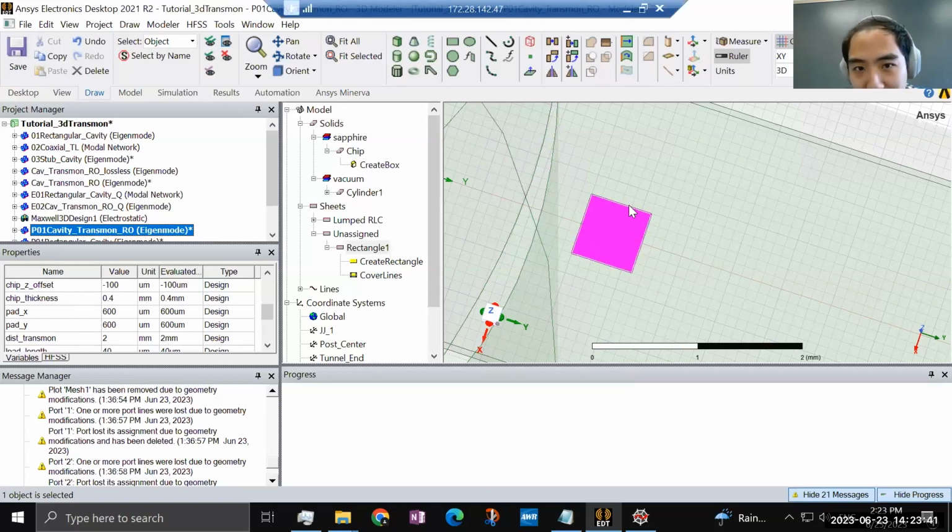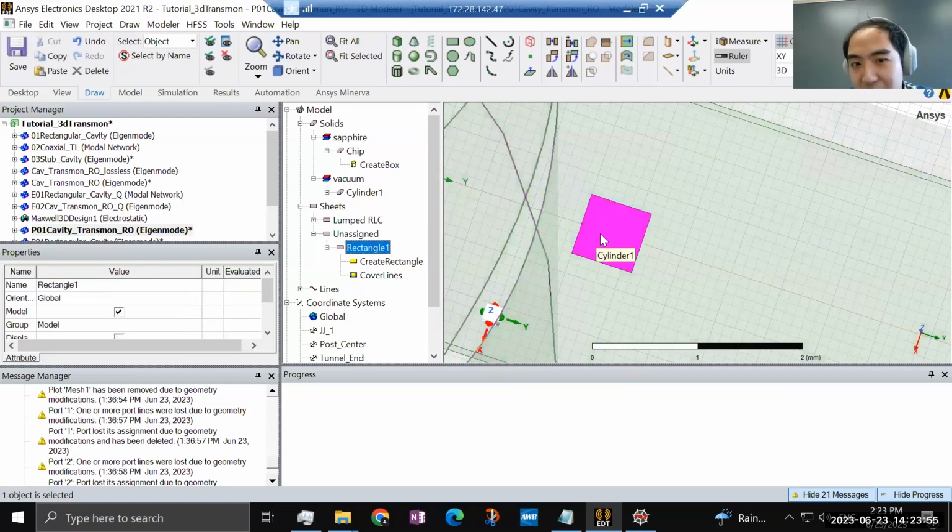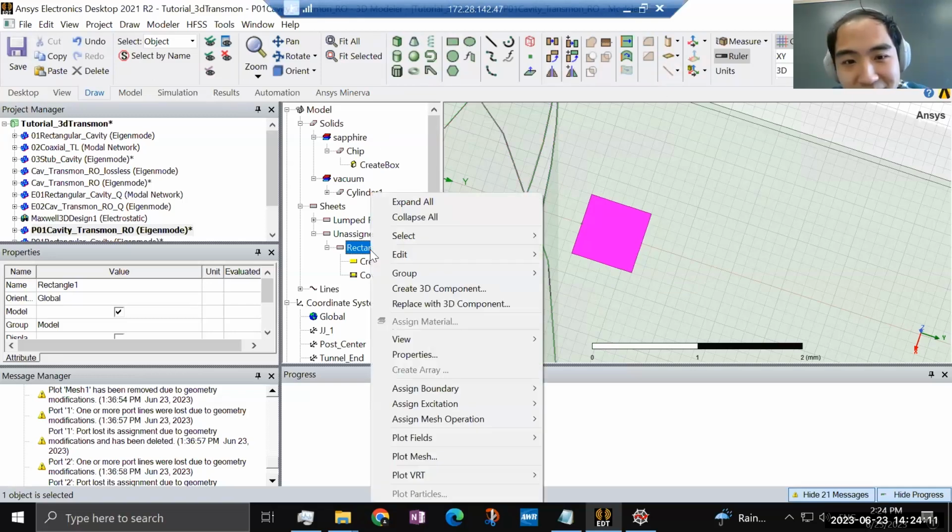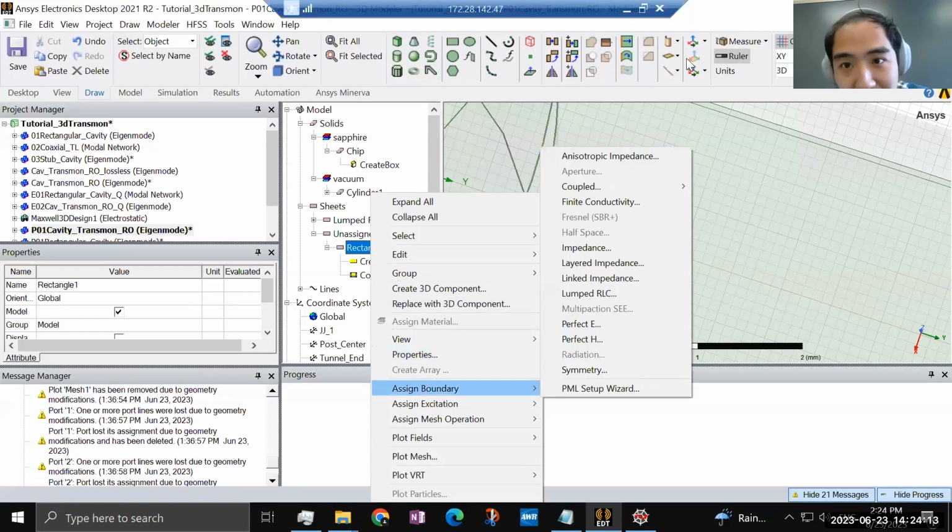So a handy trick I use is to mesh differently on the edge versus in the bulk of the 2D superconductor. This is done by creating two objects: one as the inner area of this sheet, and a separate object for the edge of this object.